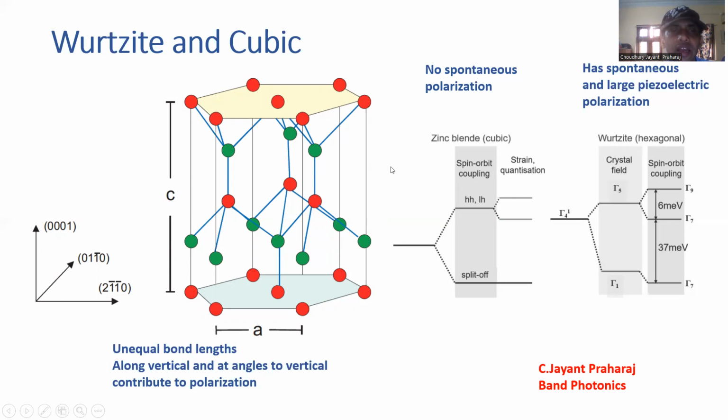Thing to keep in mind is that technologically it is easiest to get the wurtzite crystal structure, and much more growth optimization is needed to get cubic structures. So to some extent we need to build more of our devices using the wurtzite structure. And so those are things that need to be kept in mind for device optimization and also for further studies of growth optimization in these material systems.